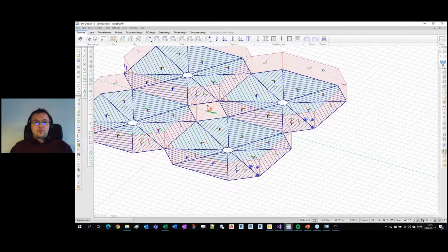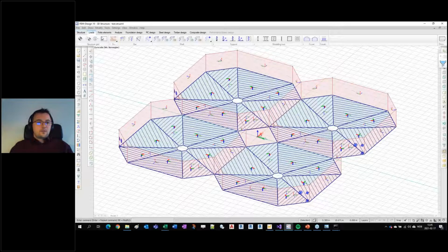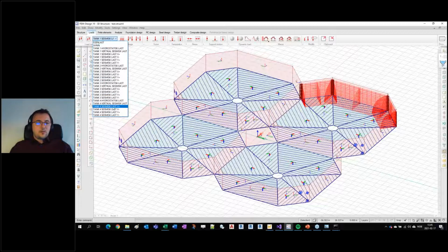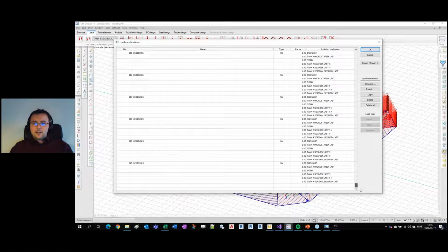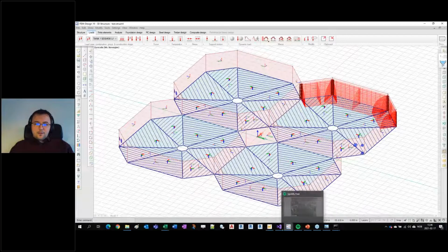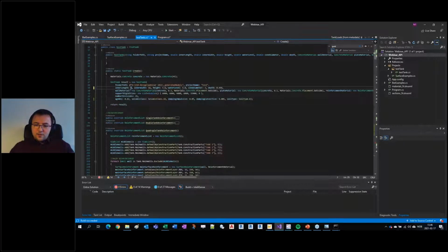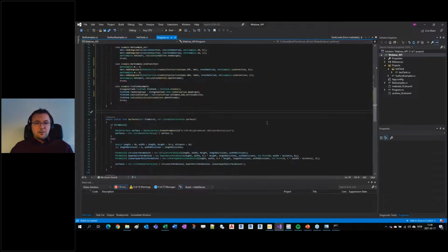So one can divide one big model into several submodels, which makes it easier to handle documentation, control, etc. Here we generated one big model with all the loads following. Of course, in this case there are a total of 26 load cases and 120 load combinations, so doing this manually would be almost impossible. I'll make changes here to show the difference between ultimate load state and seismic load state. So I'm generating now another model with the original dimensions. The only change is that the calculation type is ultimate load state.